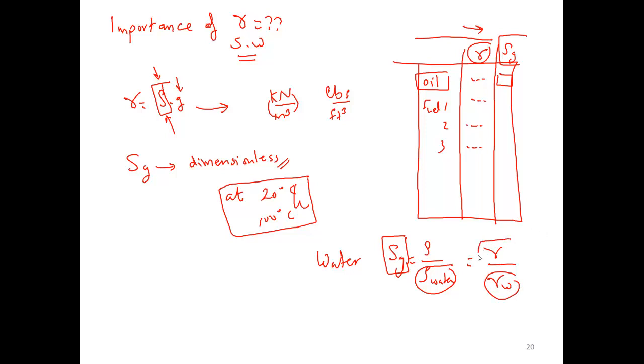And we need this actually to find pressures. For example, we need gamma to find the pressure of a specific liquid in a duct, which, as we have seen in one example, is rho G H, or rho G is simply gamma, times H. So now if we have the height H, all we have to find is gamma. To find gamma, all we have to have is the specific gravity of the liquid.